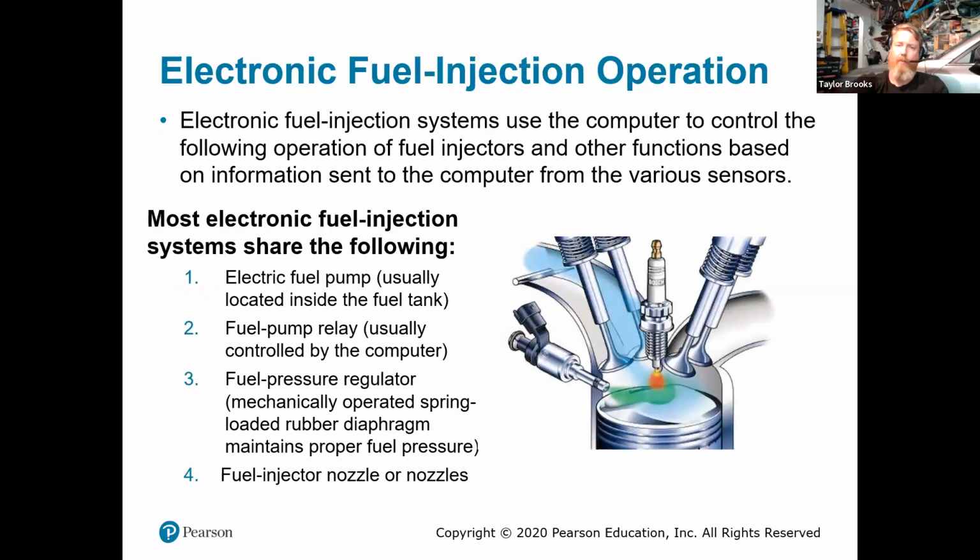For this lecture, though, however, we're going to be talking about electronic fuel injection that is involved with spraying fuel directly into the intake valve. So what's photoed here is not what we're discussing. That is going to be direct injection. So I do want to make sure that's understood because a big deal with that is the amount of pressure that's being used for either one.